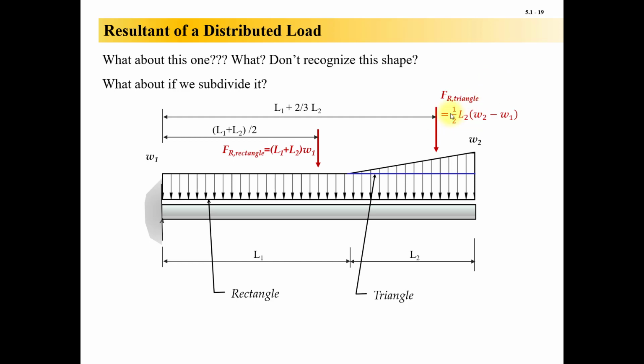Boom. So that's going to be, if you wanted to turn this into an equivalent system, you would have 2 resultant forces here. Now, what if you want to turn it into just one? You could do that. You could find the resultant by adding these 2 effects together and then saying, well, where would I place that such that the moment would be the same? It would be somewhere over in this region right here. It's the weighted average, but that was something that you did when you did the moment equivalent force system calculations in the previous work.